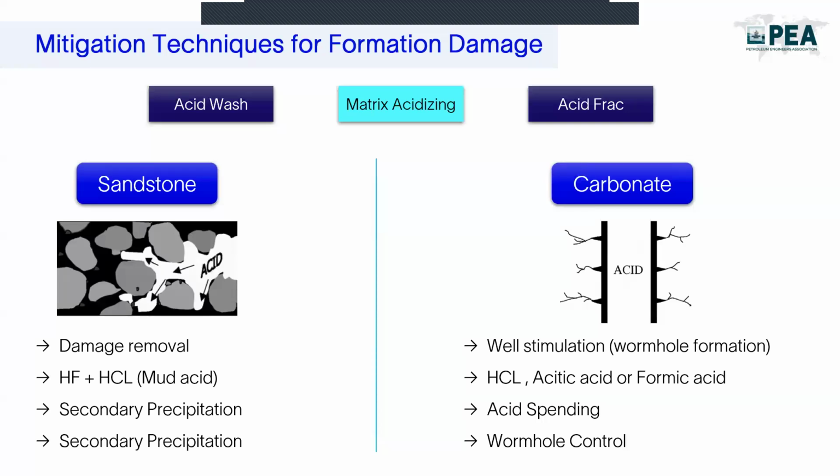So it has been said that in sandstone, it's not a well stimulation. It's more of a damage removal because the acid does not actually react, as I will talk about a little bit later, with the quartz grains, does not react with the rock composition itself.